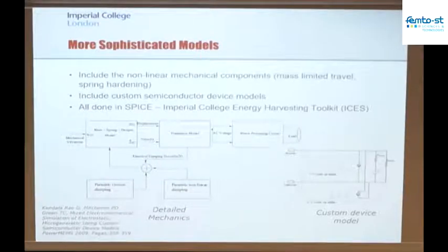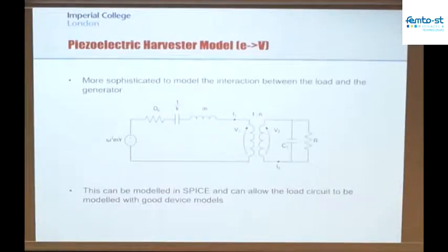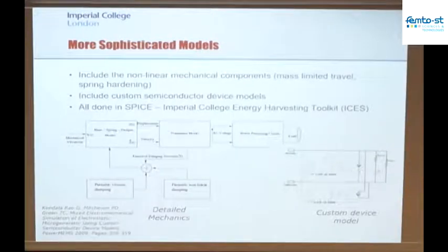If you want to go more sophisticated, because of course this is assuming a very linear mechanical system, and that may not be the case. You might need to implement springs which have nonlinear behavior. You might want to model what happens in terms of the maximum deflection of something. It hits the end stops in the device, the mass smashes into something. All of that behavior you might want to model, in which case you end up with perhaps something that is